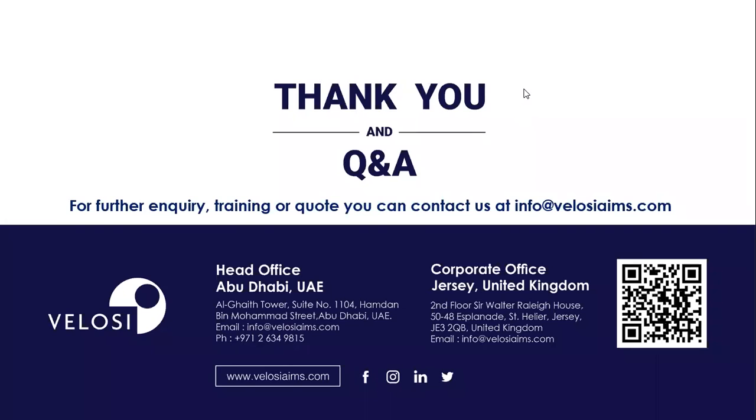Next question. We have one PSV on a pressurized vessel. Can we use PHA SIF as IPL to remove the PSV for a few hours and install it after recalibration? No, these PSVs are one of the important high pressure protection layers, and these PSVs are installed in accordance with ASME Section 8, Division 1 and Division 2 requirements.